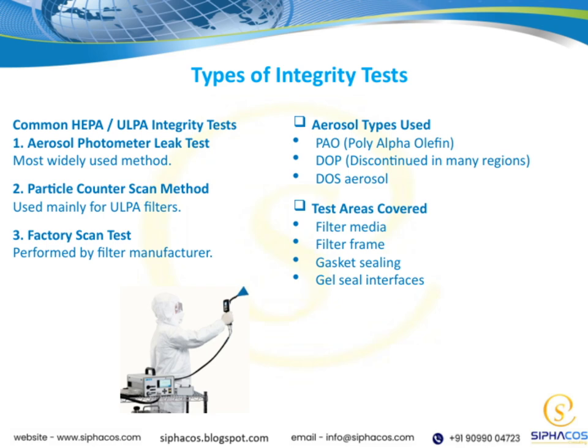When it comes to integrity tests, there are a few standard methods. The most common one is the aerosol photometer leak test, which is widely used across the industry because of its reliability and ease. For ULPA filters, we often use the particle counter scan method, which provides a detailed particle count to verify integrity. Lastly, the factory scan test is conducted by the filter manufacturer before the product even reaches us, serving as an initial quality check.